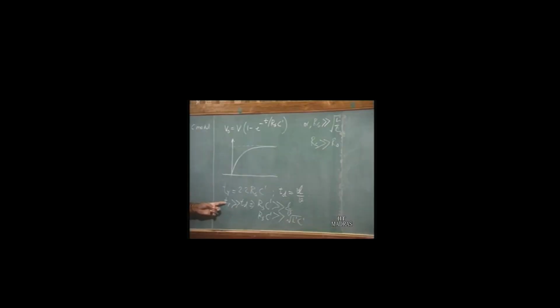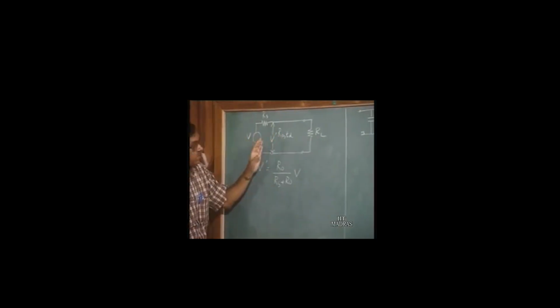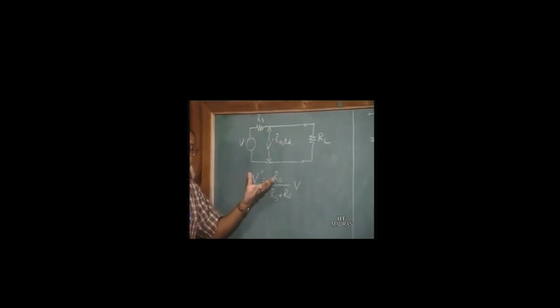resistance is very much greater than the characteristic impedance of the line, the rise time of the waveform is going to be very much greater than the delay of the line, and then we need not consider the transmission line effects. The transmission line effects become minimal, and in fact the line can be replaced by the capacitance of the line, okay, just the capacitance of the line. This is because if we go back to our earlier model, in the analysis how we have analyzed, what we have seen is that if we have a transmission line, we get the same results from using the transmission line.